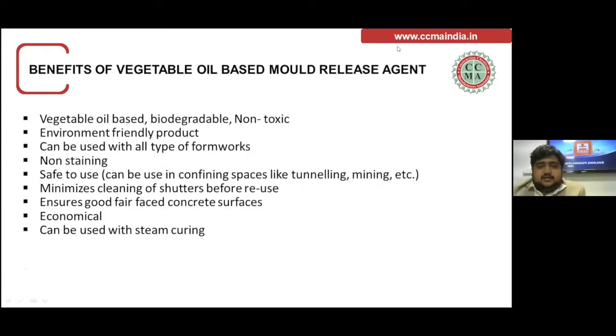The next one I was going to talk about, the sixth one, is the benefits of vegetable oil based mold release agent. The basic advantage compared to any other oil based or chemical based mold release agent is it's vegetable oil based, biodegradable, non-toxic, an environmentally friendly product, and can be used with all types of formwork. It's non-staining. There is no stain remaining on the concrete.